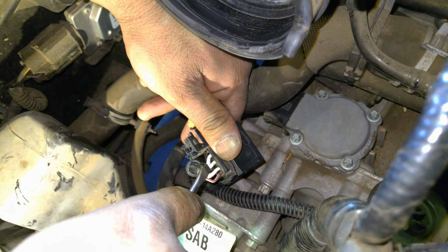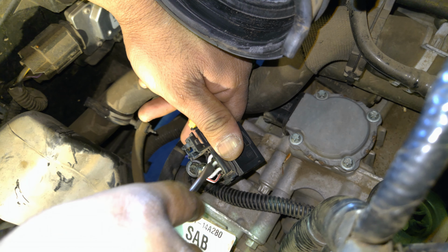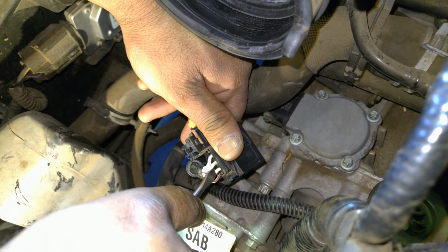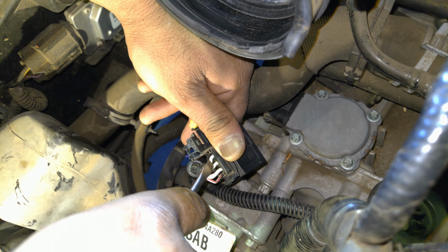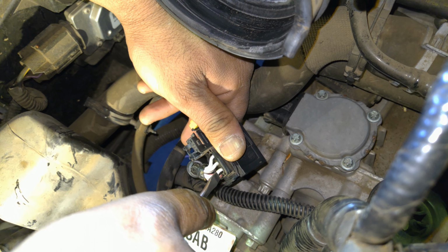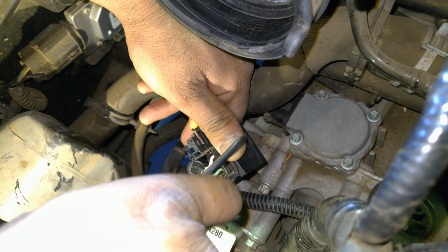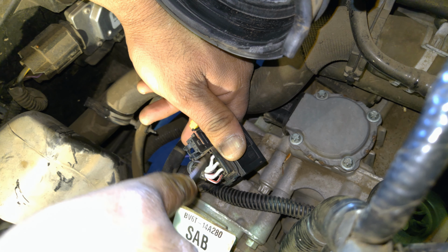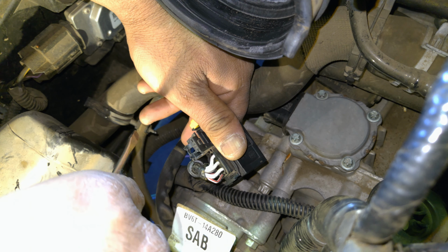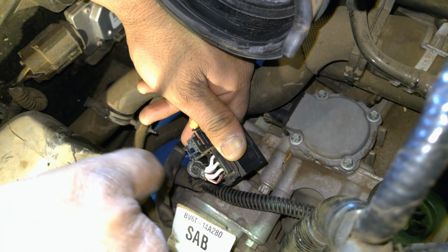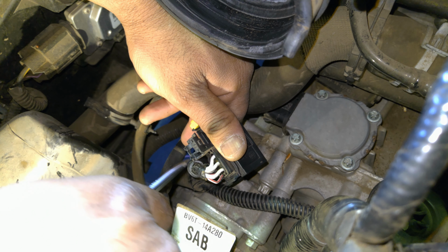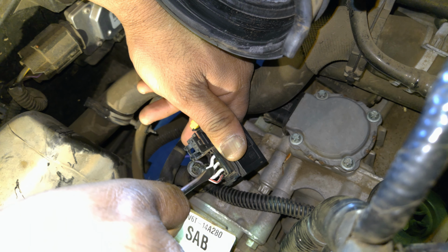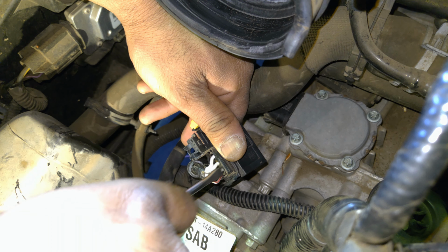So what we're going to do is get another scope signal from these wires, because I only have a 4 channel scope, so I can only use 4. So I'm going to use 2 for the bottom and 2 for the top. I don't know which one's what, but as we saw from the signal from the bottom actuator, all 3 were doing pretty much similar things. So as long as I see signals, I'm happy with it.